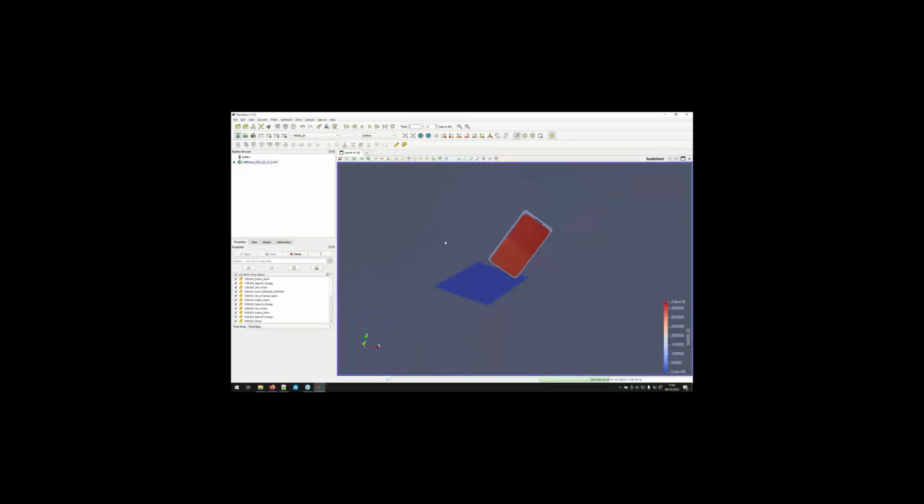Okay, so let's discover a bit of ParaView for people who are not familiar with it. The most important part of the graphical interface is here. This is the pipeline browser. This is where you open your data, where you run the analysis, and where you add filters in order to get the feature extraction I explained before. This is where everything happens. The philosophy in ParaView is that you have some data, some sources, like here the VTU file, and then you apply filters to do post-processing and analysis, and then you display the output of each filter.